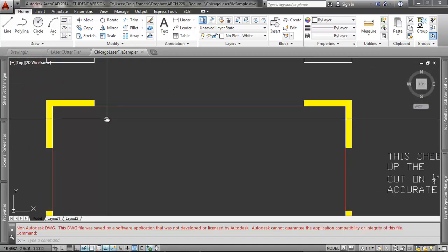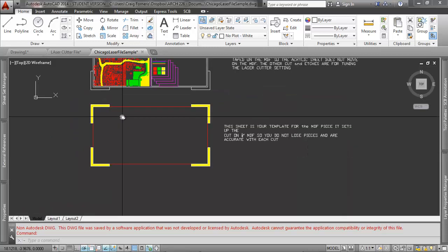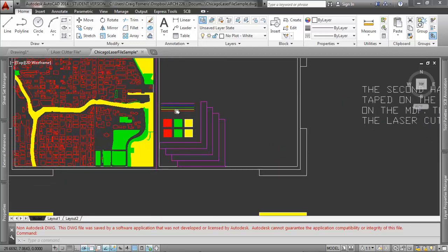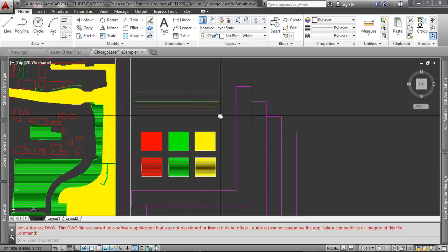And so essentially you're recreating your own laser cutter bed that has 0, 0 marked accurately. Because right now when you get to the laser cutter, 0, 0 is always arbitrary. And you've always got to kind of guess where it's at. This will make it so your 0, 0 is always exactly the same when you cut it on the bed. And then these other lines are set up for you to fine-tune the laser cutter settings. So you'll run through and get it so the pieces just barely cut all the way through, so you can try and use less tape when you pull this out.